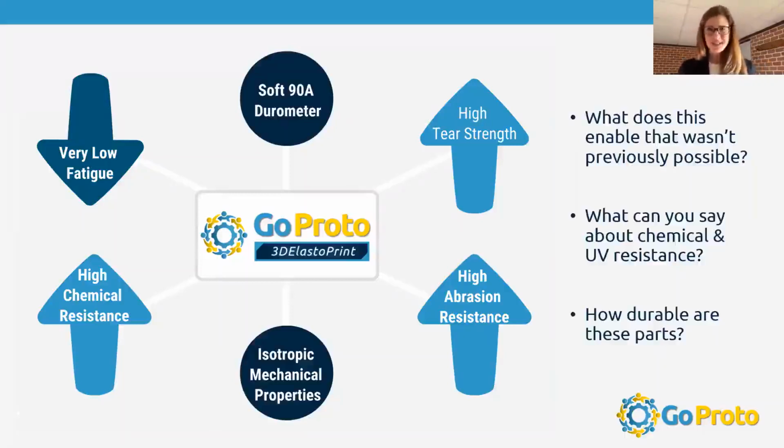So we're doing a lot of testing, and of course, it depends on your application. With water, it's fine. Dilute sulfuric acid, it's fine. Sodium hydroxide, it's fine. Some oils, you have some weight gain, and some alcohols, we're going through them because you can have some challenges there. So it really depends on your application. It's not going to be PEEK. It's not going to be PA12, but it sounds like based on some of the options available today, that it does have some different or increased properties for chemical resistance.